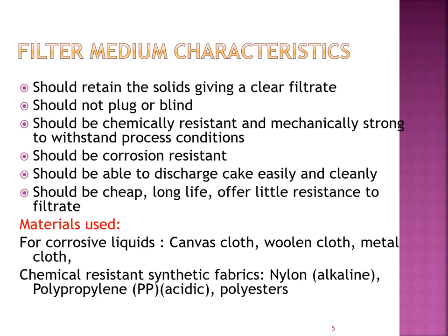The characteristics of the medium include retaining of solids to give a clear filtrate, should not plug and bind, should be chemically resistant and mechanically strong to withstand the process conditions, should be corrosion resistant and should be able to discharge the cake easily and cleanly. The medium should be cheap, it should have a long life and offer little resistance to filtration.